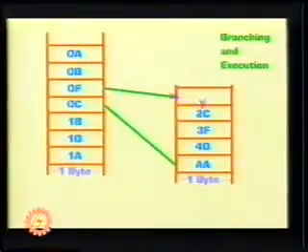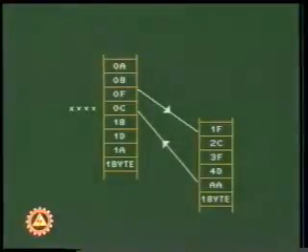Sometimes it becomes necessary to branch out from sequentially stored instruction to a memory store, where a set of instructions are stored. After executing those instructions, the processor resumes the execution where it left earlier. In such situations, it is required to save the return address and possibly status of some of the general purpose registers before branching.